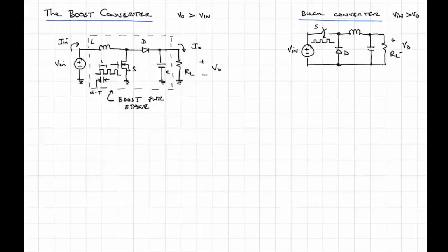Now what we'll be doing in the lab, we'll be just building this power supply, or this power stage. We will not be building an entire supply. And the pulses that we will be supplying to our transistor will come from a function generator and not from some control circuit that is monitoring the output voltage and then changing the duty cycle dynamically. So it's kind of like running the engine on your car without some cruise control, right? That's looking at the speed and adjusting the throttle. We're going to run it in what we say is open loop.